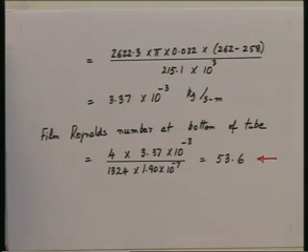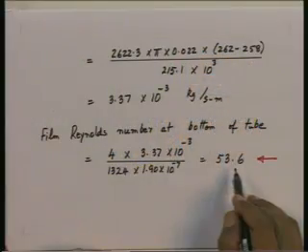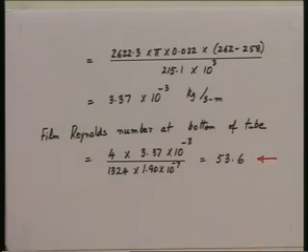Now, you might want to note that the Nusselt formula which we have given is generally experimentally found to be valid up to film Reynolds numbers of about 30. Above 30, ripples form on the condensate surface, because there is more condensation taking place. Film Reynolds number higher means more condensation rate. These ripples tend to enhance the heat transfer coefficient a little. It is still a laminar flow, but they enhance the heat transfer coefficient by 10, 15, 20%. This is what is observed experimentally.